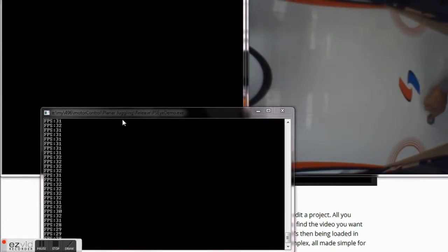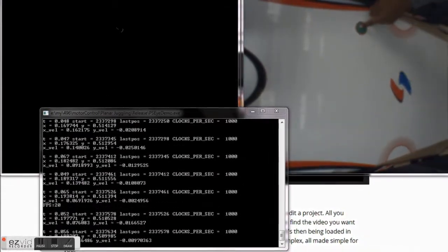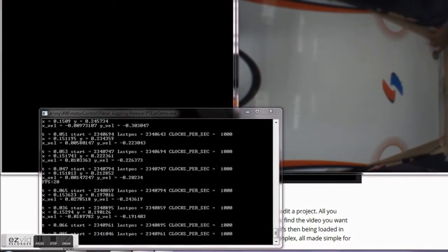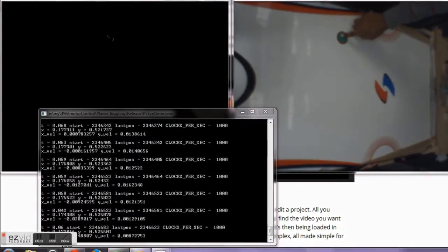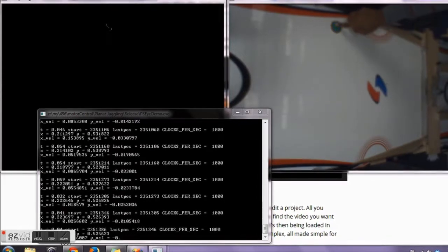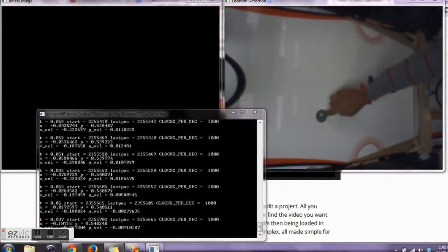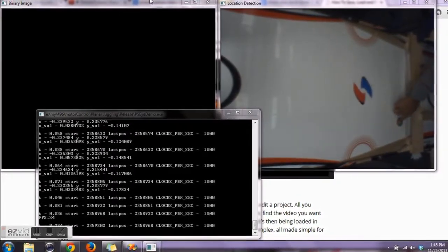Seen here is the vision code output windows. Notice how the command prompt begins to display the puck data as soon as the puck comes into view. The software uses hue saturation value filtering to obtain the green value from the image and then finds the center point. If you look closely, you can see that the code then draws a blue box around the center of the puck. HSV thresholding was the selected method of filtering because it allows us to put our hands in the frame without issue. Background subtraction, the other alternative, does not allow for this, and the testing process is much more tedious as a result.